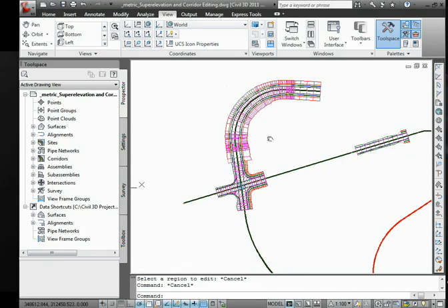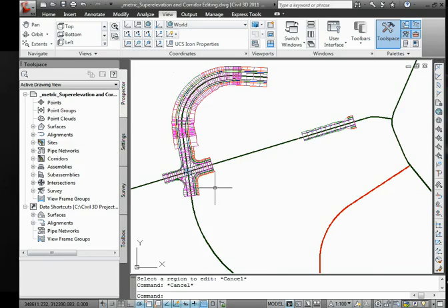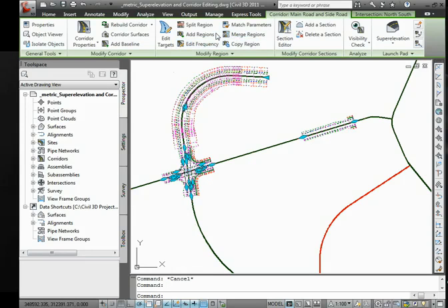Let's look at the area south of the intersection. In this area, I'm going to use the Add Region command and just pick my baseline from the drawing, the proposed side road. Again, I'm going to use that red marker to pick a station that abuts that adjacent region. And then for the end station, I'm just going to key in a value that I know I need, 375.